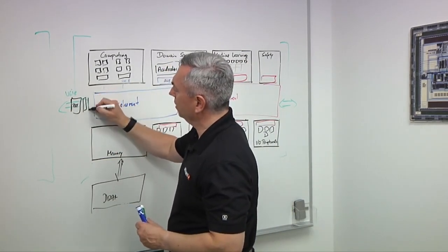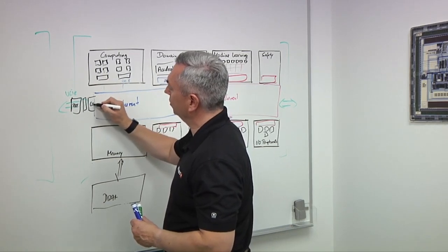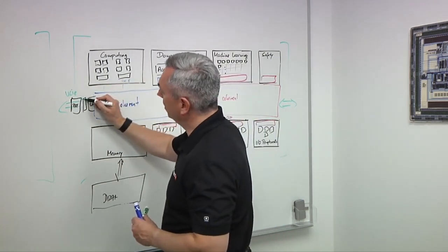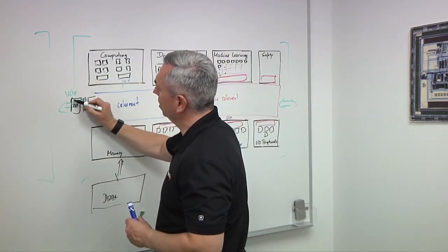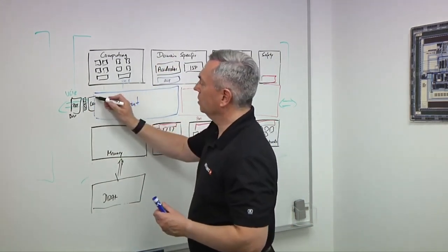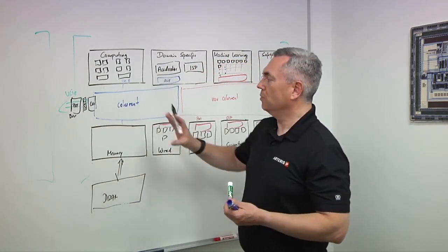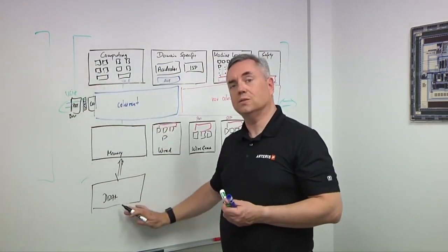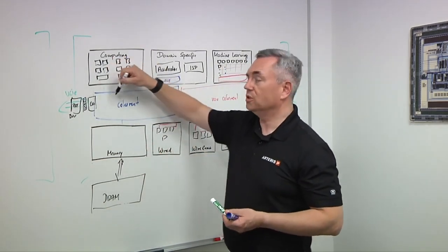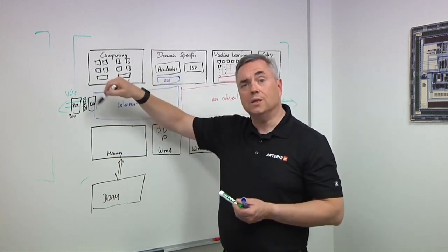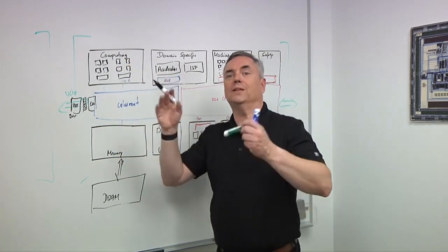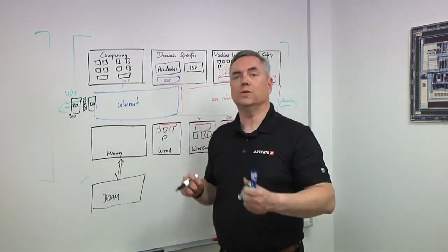And then you have a protocol stack where you basically say, okay, here I have, for example, a CHI, the coherent hub interface from ARM going in. I may have CXS here, and then I have UCIe, or to be fair, a bunch of wires to go over here. So as I consider all this, I now need to understand, will these actually both have to access this memory? Then cache coherency needs to play, and then all the effects like snooping and so forth need to work. Those are all built in the CHI protocol, that you basically figure out who has the last valid item in the caches, and then a whole lot of coordination goes on.